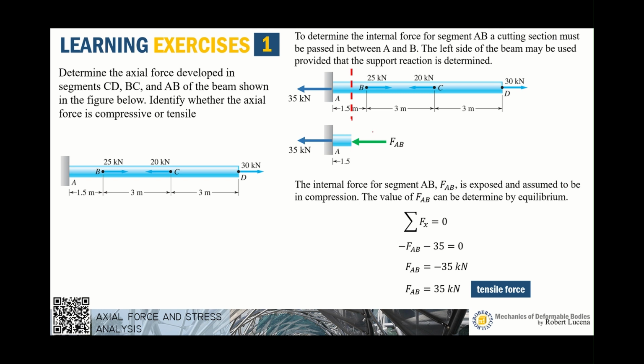If you get a positive value, that means your assumption is correct and this is compression, but it's very obvious from the beginning that it will not be a compressive force since it has to counteract the external reaction.